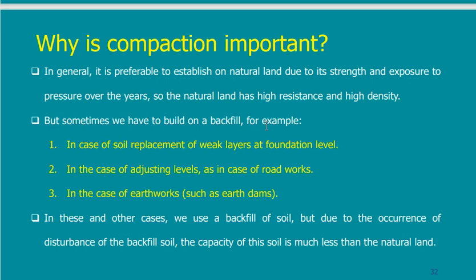Why? Because just adding or dumping soil on top of the natural ground means that it can settle a lot. It's not compacted at all. So in this case, I may have to add layers. I will just put a small thickness of layer and then compact it. Put another small layer and compact it, and so on.